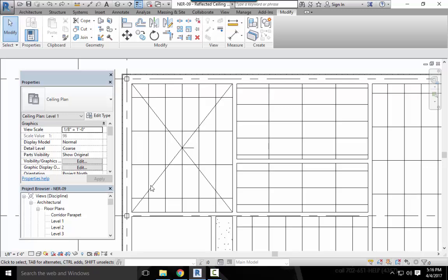So when you're thinking about how to lay out a ceiling grid, especially 2x4, 2x2 is a little bit easier. It's all square. Or in a room like this where we have pendant light fixtures, it's not as important. But when you're doing typical lay-in fixtures, which is what most rooms have in them, you need to think about the lighting layout. So this is a conversation that you would have not only internally with your peers in the architecture field, but you would involve your electrical engineer and say, hey, how do we intend to light this room?